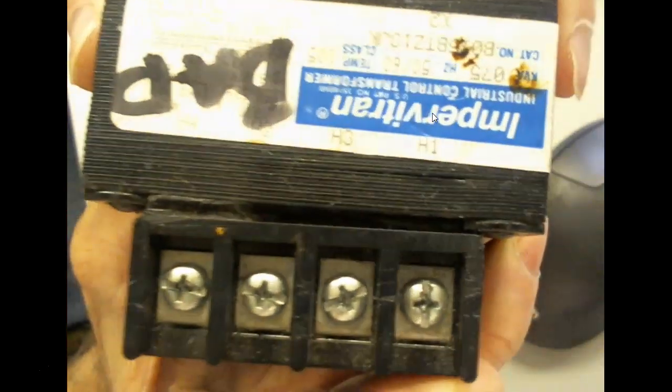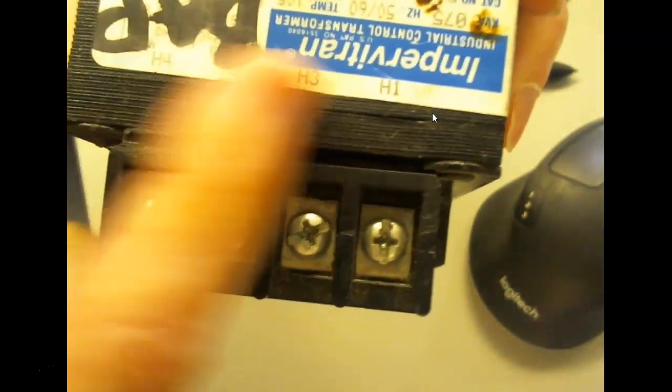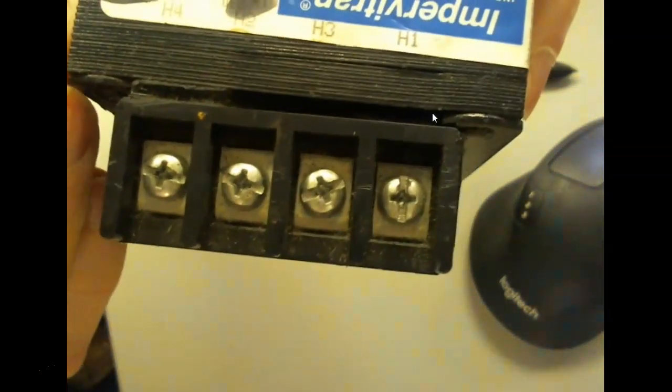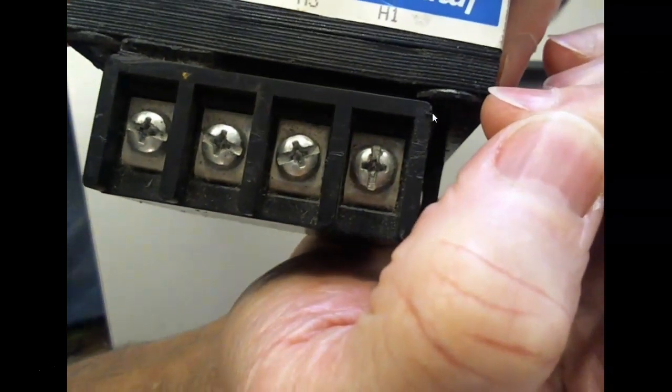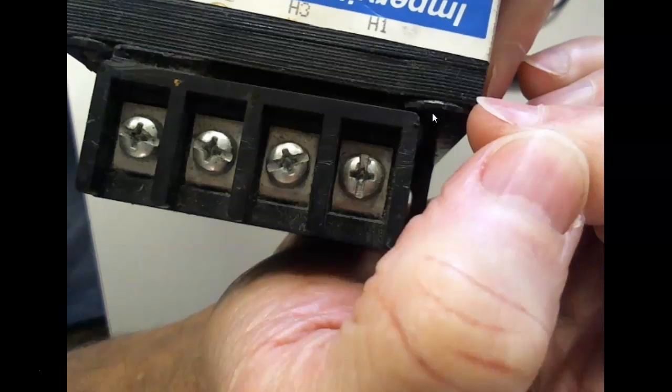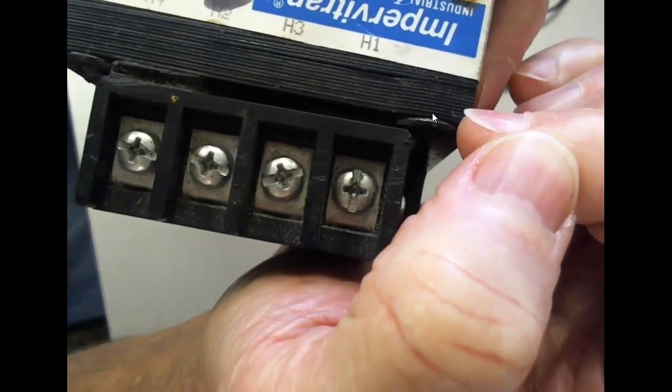Like I said, I don't know if we're going to be able to focus this in. So you can't see the windings anymore, but you can definitely see the lamination. Can y'all see the little stripes there? Each one of these is another set, and the voltage and the current being induced in this one will not combine with that one, will not combine with that one. So they're coated with a really thin coating of insulating paint.